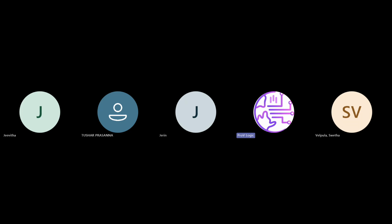If you generate other values, suppose 3, 4, 7, 8, 9, 10, there is no use of generating those values. Why? Because we are not doing any operation for those commands, right? We are doing operations only for 0, 1, 2, 5, 6. So according to that, we need to generate the input scenarios. If you generate other scenarios, no use, even for coverage. So this is the controllability we can do in SystemVerilog.